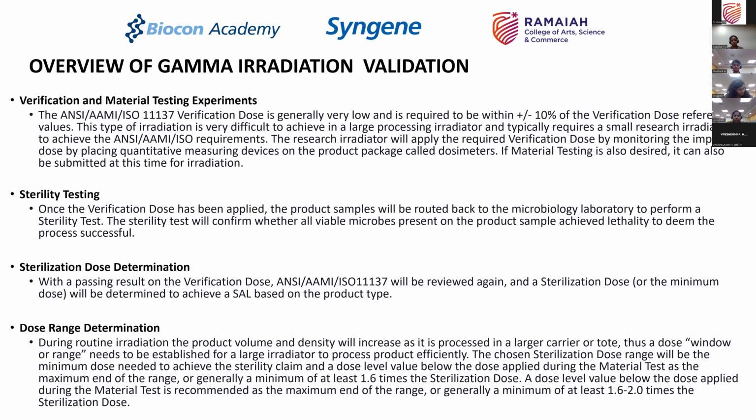You always say 123 plus or minus 2. You never say 121 degrees centigrade. Why? Because there are variations. Your steam pressure will vary, your moisture in the steam could vary, your temperature would fall because of a certain valve opening out and allowing the condensate to go out. Similarly, you do not want to go below 121 anytime. So you fix a range and say, I will do my sterilization at 123 degrees centigrade, and I will not allow it to fall below 121 degrees centigrade on the lower side, and on the higher side I will not go to 125, because I have a possibility of charring the material.